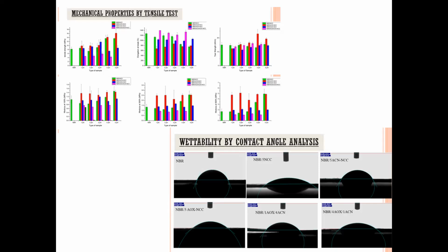If we are talking about hydrophobicity, due to the addition of the acetyl group, we have managed to change the hydrophilic properties of the nanocellulose brought by the hydroxyl group and make it more compatible with the NBR matrix, which is hydrophobic in nature.